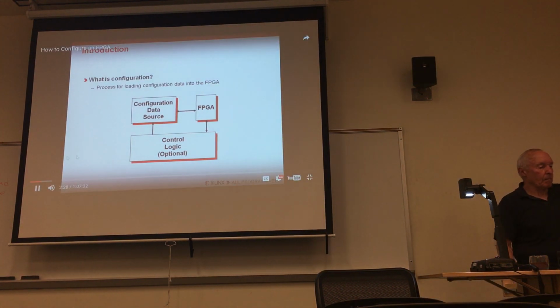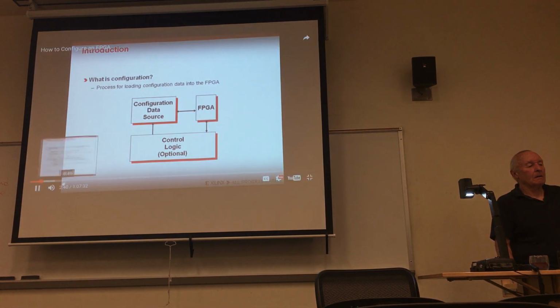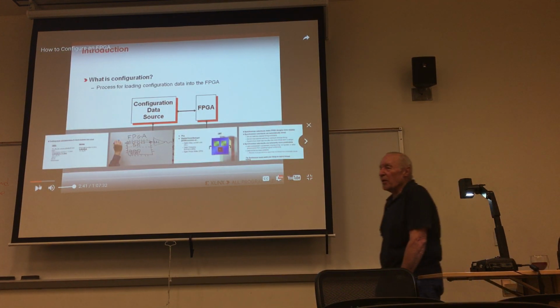This brings to mind the question, why are FPGAs made with SRAM logic and not flash if reprogramming is going to take extra effort and cost? Well, the answer to that is that SRAM cells are much smaller than flash cells, and FPGAs offer much larger densities. Okay, so that's an important point.